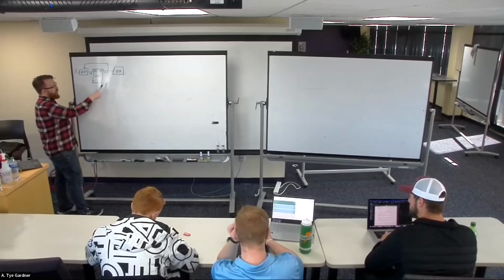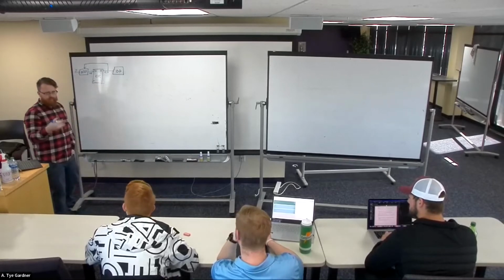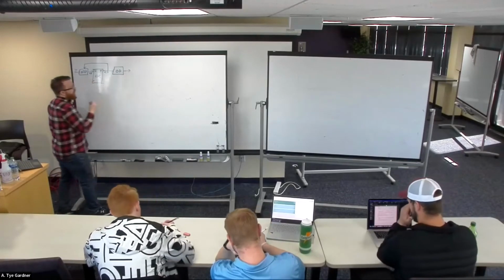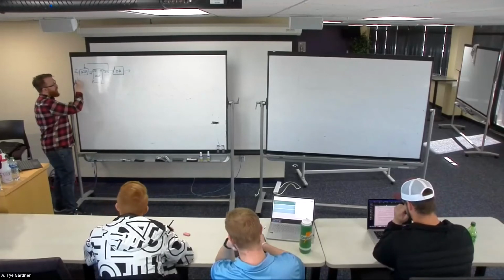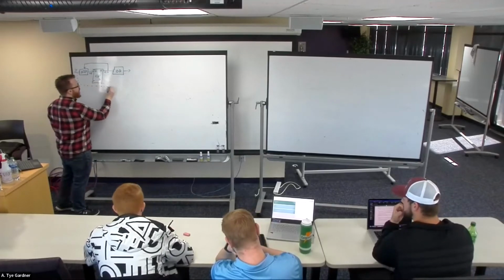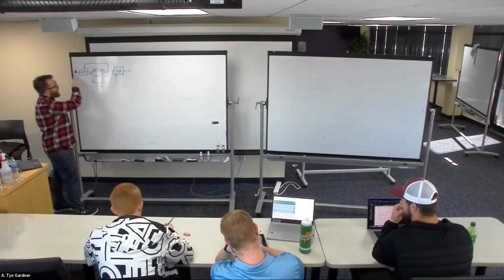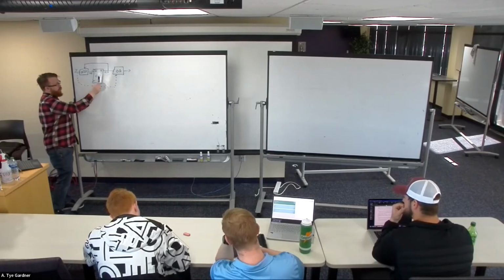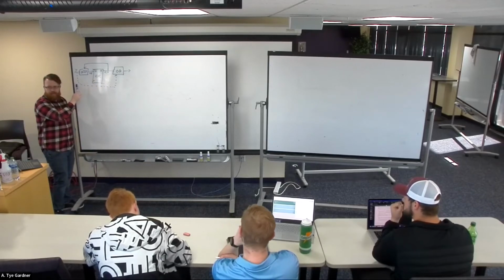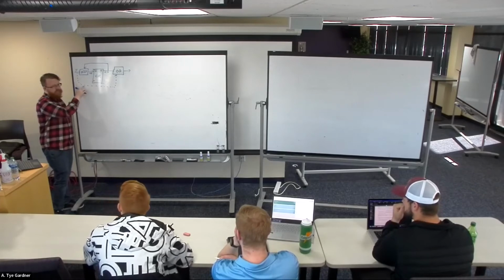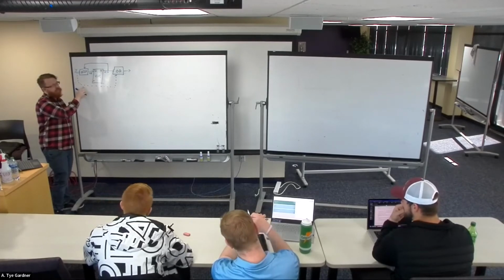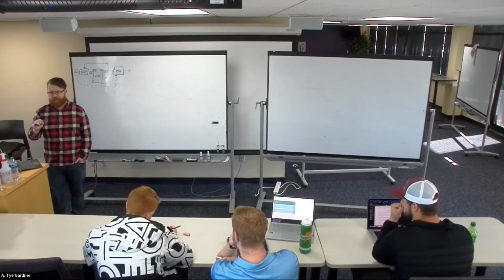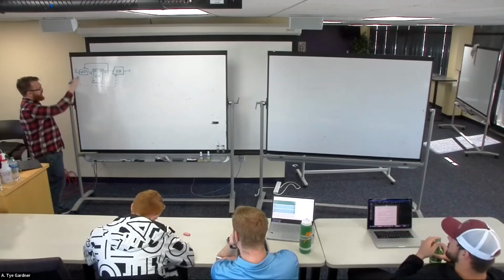The other purpose of the current state is, what are my outputs during this state? However, the output decoder can be more complicated in that it could potentially also care about the inputs. Do you remember what the difference between the two types is? Like, do we remember the names? Mealy and Moore. If I have this connection, is it Mealy or Moore? Mealy, because in a Mealy, the outputs depend on both the current state and the input. That's the most important concept around this structure.